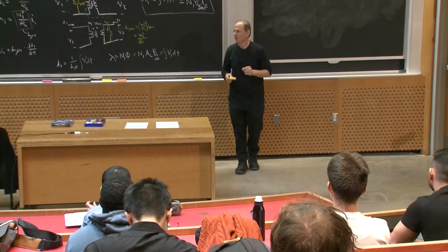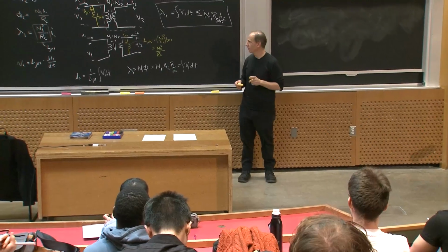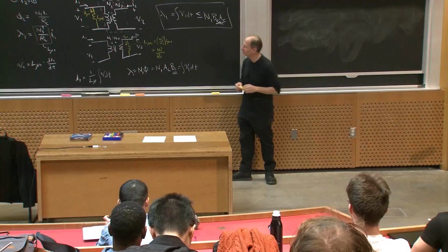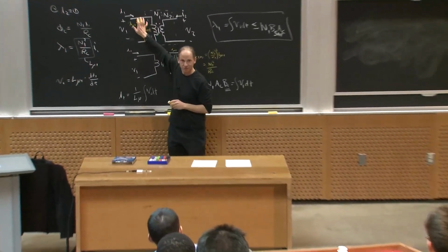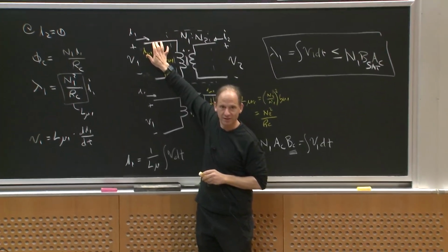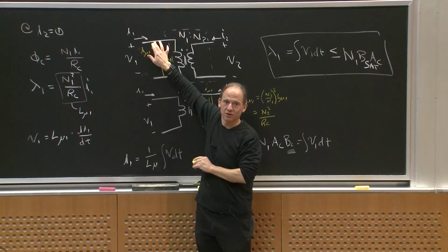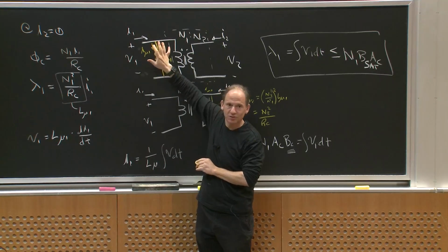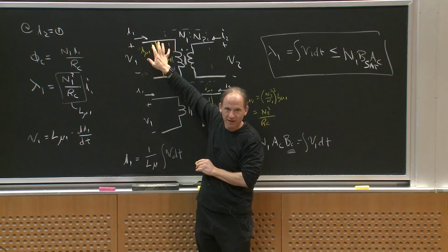Sort of. There is the notion of applying a voltage for a little while and storing some energy in this magnetizing inductance, right, which is sort of what you just said, and is exactly what you do in certain kinds of converters. So in some kinds of converters, we will actually use this parasitic component to our advantage, and we'll talk about how you design for that.